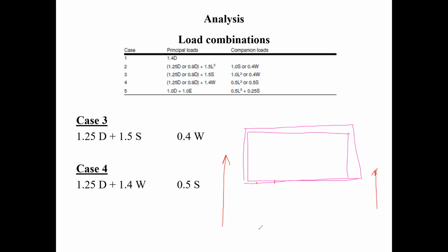So what's going to happen? The wind's going to blow on the stud here. As the wind goes through the house, it's going to pull the air away from this wall, and there's a suction on the internal one, and then it's going to be pushing on this wall here, and then as the wind goes around the building, it's going to be pulling away from the building. So there's your external one. You see how it happens? All right, perfect. I understand now. That's very clear.